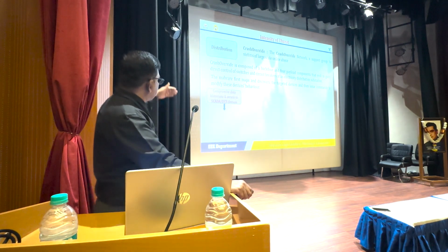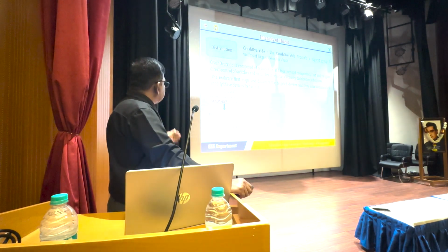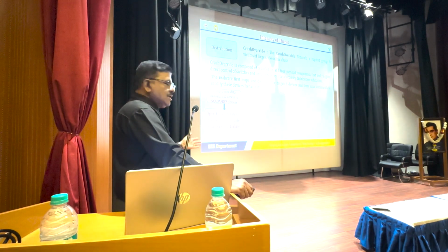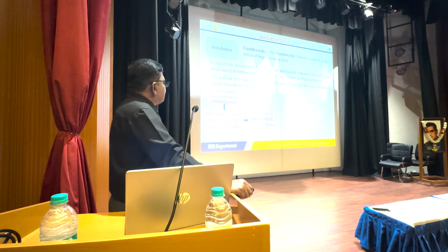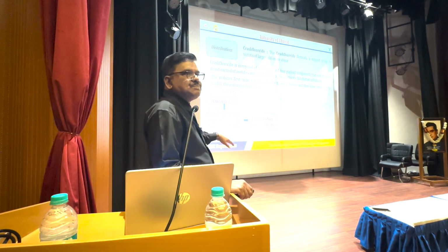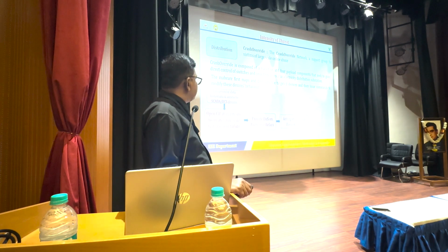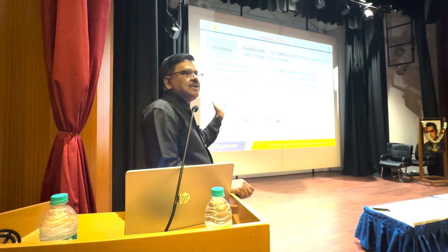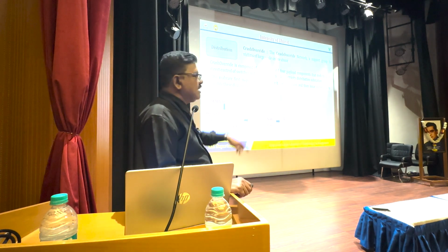You see, first it compromises the data historian and accesses SCADA DCS devices, through which it will open the circuit breaker at the victim side. So it will create a large transmission failure. Then he will execute a denial of service on protective relays. That means the protective relays become unresponsive. Then it leads to an unanticipated physical reconnection. Now the circuit breaker is open, and suddenly he will close the circuit breaker.